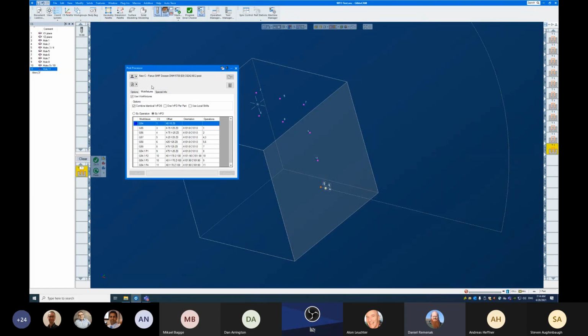You can also run into this on a 4-axis part if you're machining in the same CS but using rotations. If one operation starts at 90 degrees and a different operation starts at 180 degrees, those are potentially different positions on the machine if you're off-center.